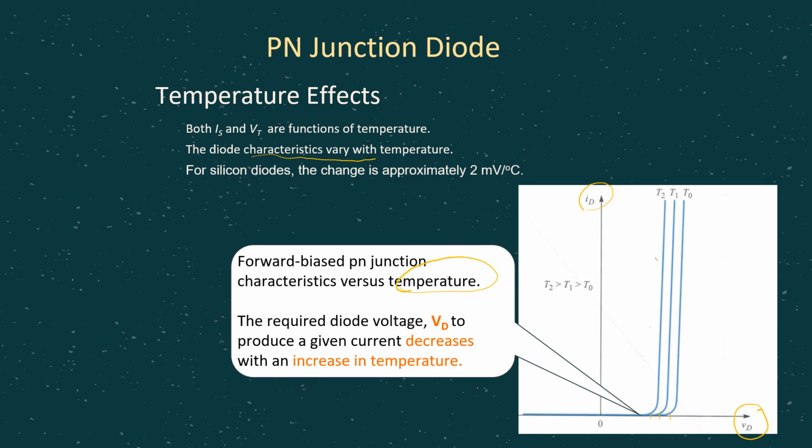Okay, so it means that it just needs a little bit more voltage connected to the diode for them to be able to produce current. Meaning to say, in this case, the higher the temperature, the lower the V gamma value. Why? Because the diode is also getting energy from the temperature. So if the temperature is higher, the diode is getting more energy from temperature. Because of that, less voltage is needed to turn on the diode so that the current can flow.